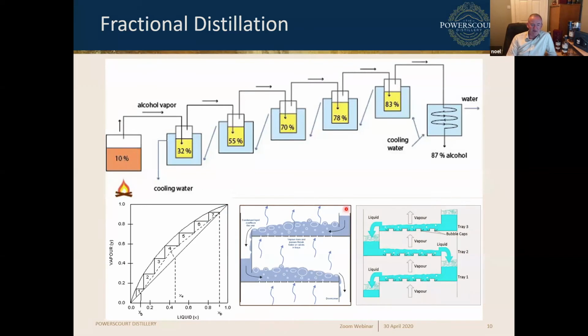So on that diagram, the liquid comes in at the top of the column. Now this column could be 40 foot high or more, and the liquid is usually entered in about maybe 4 plates from the top, and it will flow down through the column through a series of downcomers and weirs. So coming down on the right hand side, it flows across the plate, and at the other side is a weir which it has to flow over to get down into the next plate.